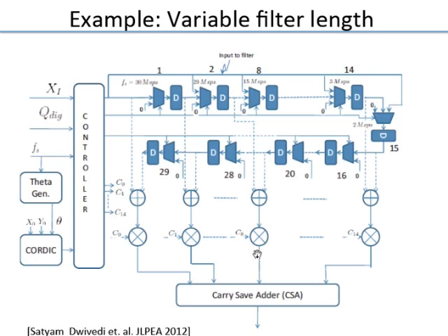So you have really suppressed the activity in a portion of the chip just by setting the values to be fixed values. Because these are all zeros and the nature of the computation is addition, in a filter you add products, and if you add a 0, nothing changes. So it is a very simple way of doing this. You can also have coefficient 0, but then only from the multiplier onwards you will have no activity. So yes, you can also do it that way.